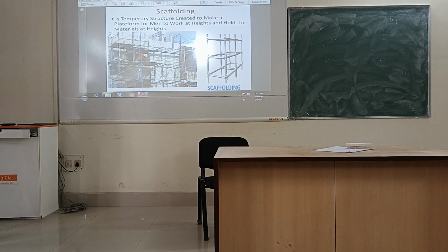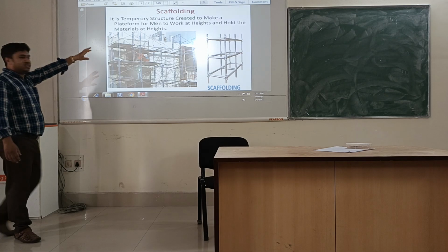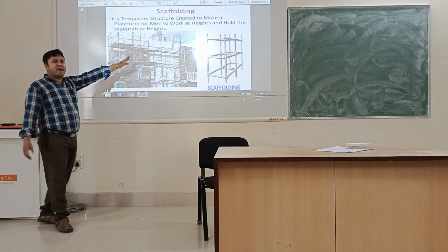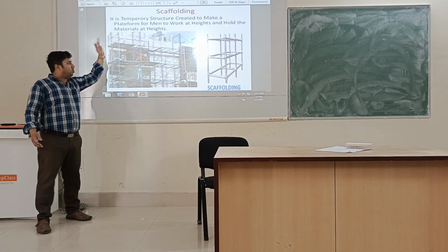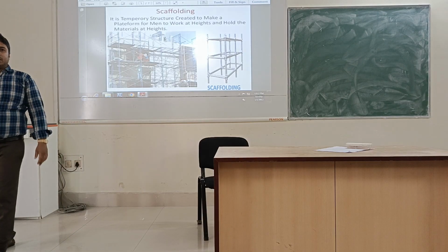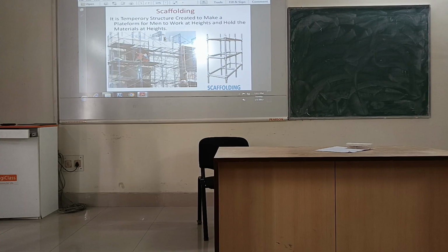Okay, understood? This scaffolding is not carrying the load of the structure. Scaffolding is only a temporary structure which is prepared to carry the load of the manpower who will go to an elevated position and prepare your finishing work, like your repairing work or your plastering. Okay, for any checking of the finishing work and all this. So it is a platform actually. It works as a platform.